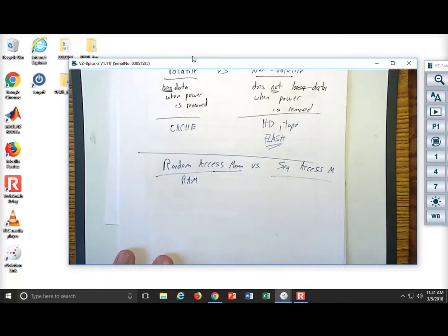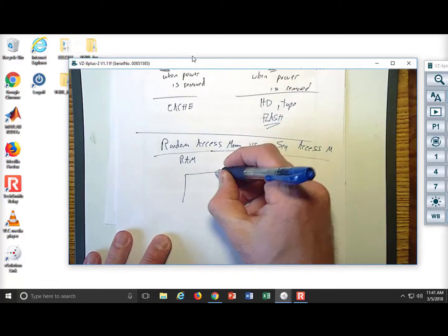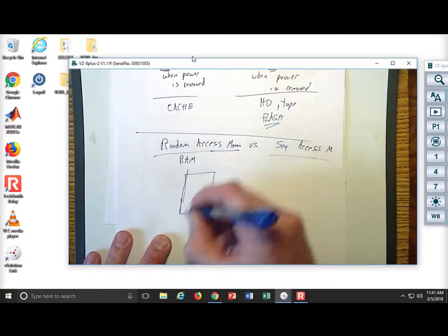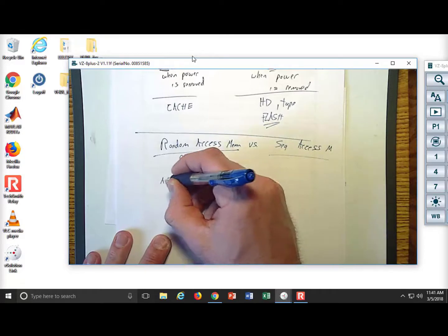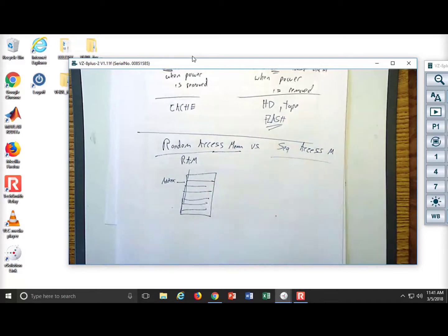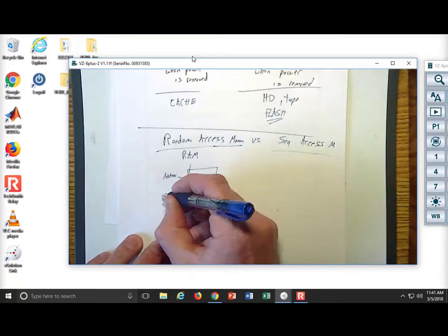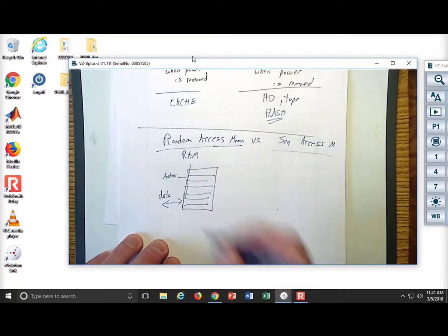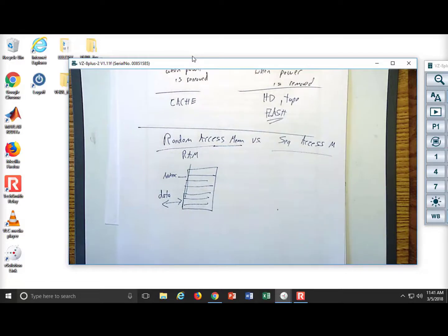But random access memory simply means that you can come along, and you have some sort of address. You provide an address to this puppy, and it will spit back the data no matter what address you give it. And this is very intuitive, the way that we just described a memory system using an array. You give it an address, and guess what comes out? The data. Guess what goes in if you want to write to it? The data. You can access any memory location at any given time. It is random access memory.